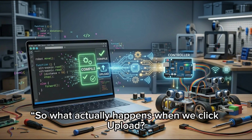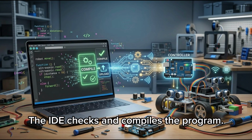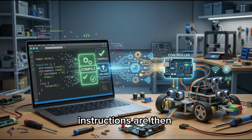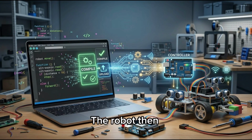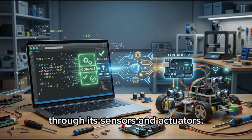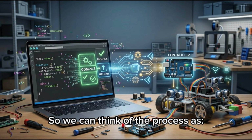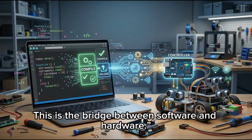From code to robot. So what actually happens when we click upload? First, we write our source code in the IDE. The IDE checks and compiles the program. The resulting machine-readable instructions are then transferred to the robot's controller. The controller stores and executes those instructions. The robot then interacts with the physical world through its sensors and actuators. So we can think of the process as program, compile, upload, controller, sensors and actuators, robot behavior. This is the bridge between software and hardware.